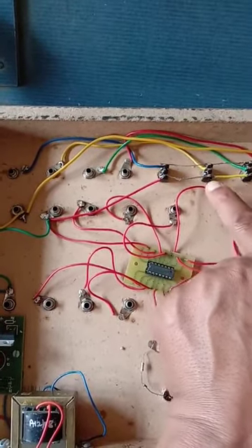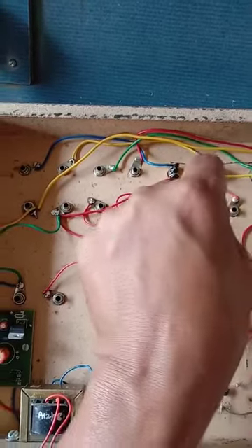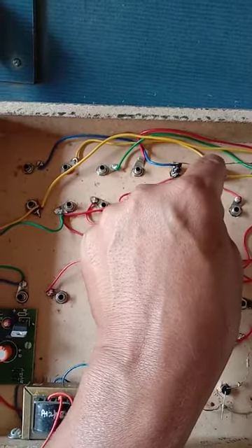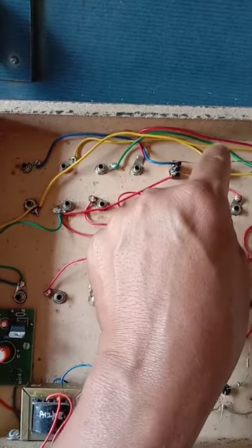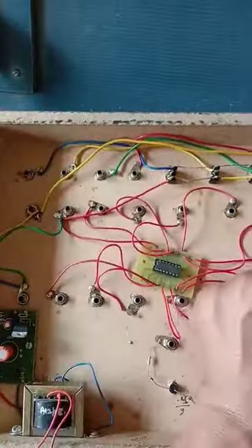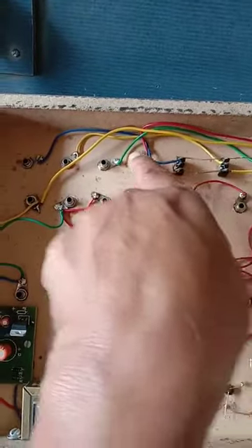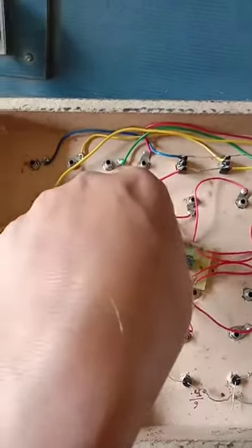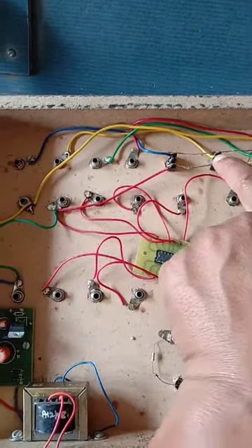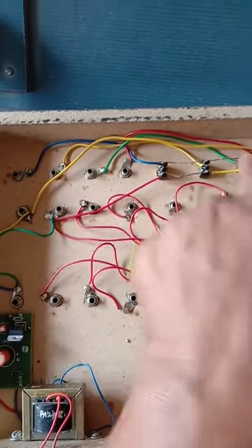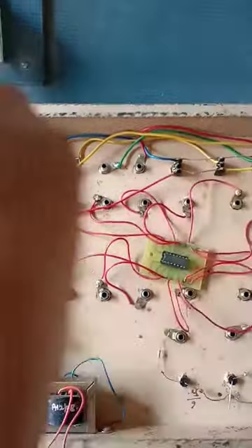When the input is connected to plus VCC, the input becomes high, and when it is connected to ground, the input becomes low. So one side is connected to plus VCC and the other side to ground, and the actual input is connected to this middle terminal, the pole. So this is a one pole two-way switch, or SPDT switch.